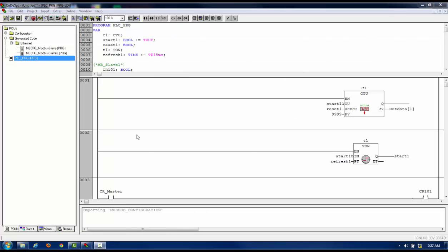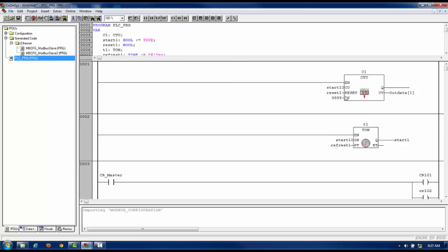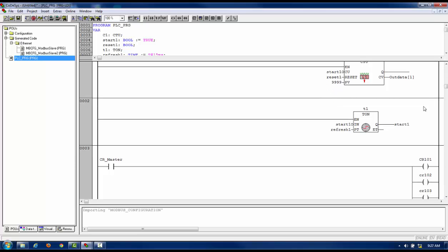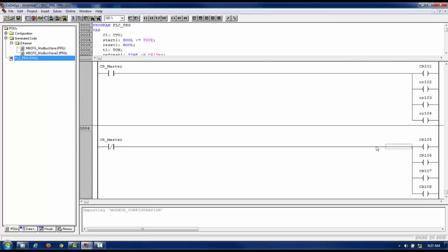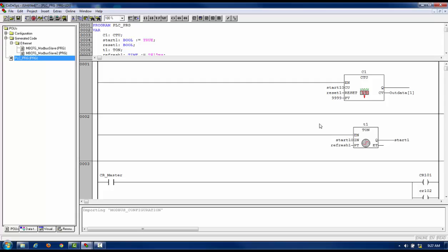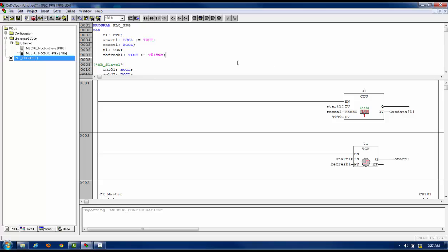So here we can see in CODESYS, under the POU tab in the CODESYS tool, I've just created a few lines of code, trying to speed the process up a little bit, just to create some data, something to transmit, if you will, to send to the slave devices. So just writing to my OutData1 here, for example, you can see if I come up here, I have an array of information, OutData1, an array from 1 to 128.